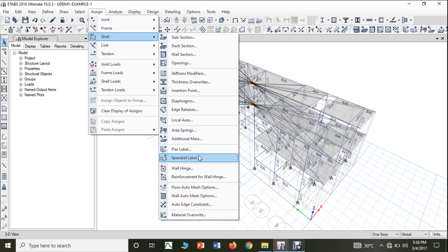to some extent the behavior of the steel as well as the behavior of the reinforced concrete structure is completely different. So when it comes to the steel, after a certain loading there will be a formation of the hinges. So whenever there is a formation of the hinges, it is an indication that the maximum load has been taken by the structure.